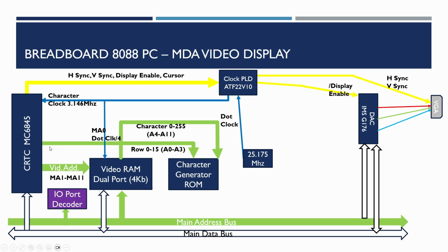This will have a VGA 8x16 font, 16 rows, 8 bits across. And this is driven by the raster address or row address coming out of the CRTC. So the first 4 address lines of the character generator ROM are from RA0 to RA3, going to A0 to A3, and then the video RAM, in fact, outputs 1 byte to choose which character, and those character values 0 to 255, 0 to FF, then go to the A4 to A11 lines.